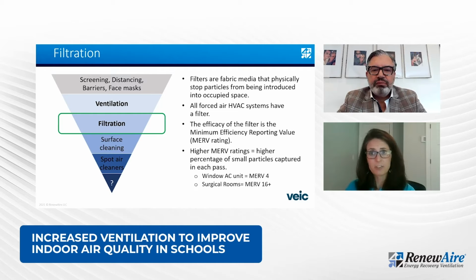And filters, you're used to them in your everyday life. You've got them in your automobiles, you've got them in your window air conditioners, in your furnaces, in your home. The filters are the physical, usually fabric media that is physically removing the particles from the air. So anything that was in that airstream is going to then be captured on that filter. Filtration and the number of air changes, they go hand in hand because you need to physically move the air over the filter for the filter to be effective. And the more times you're moving the air over the filter, the more of the particles you're going to be able to remove from the airstream.